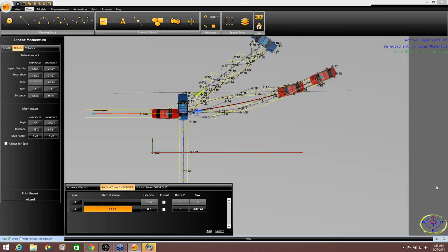In this case, I think we did it 3 times. It was a 0.19, a 0.20, and maybe another one. It was right around 0.20. Maybe it was a 0.21, 0.20, and 0.19. So we figured a 0.20. And this was 10 years ago, so I'm trying to rack my brain to remember what it was. But we did a rolling friction test on the cars to see what the rolling friction was.